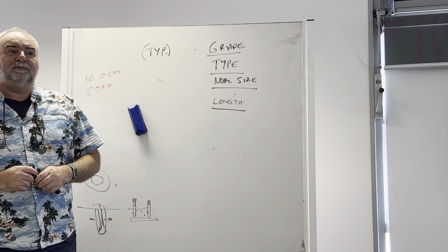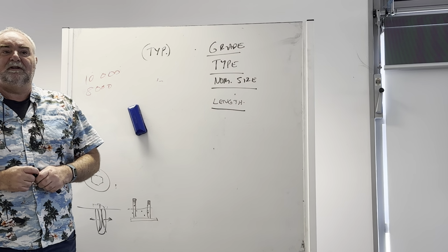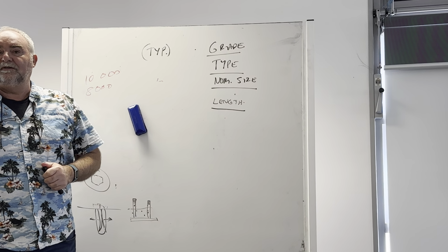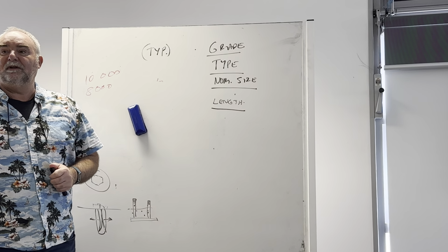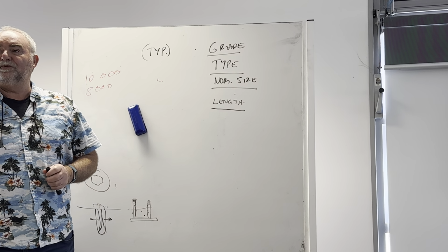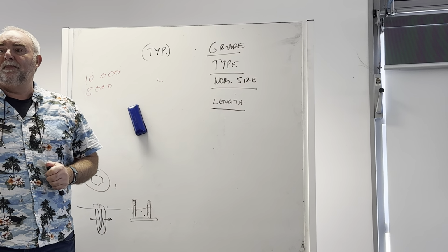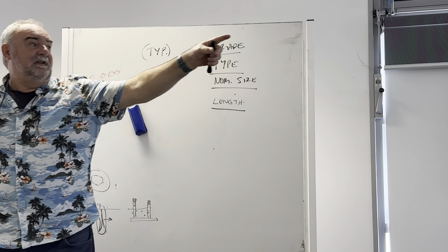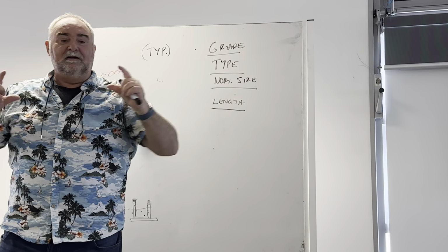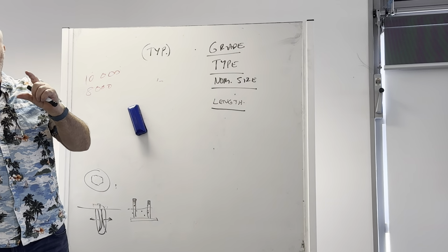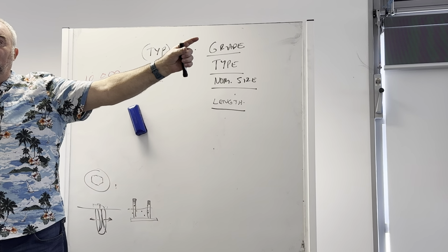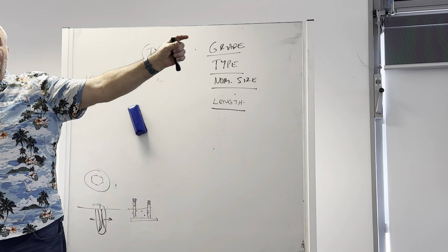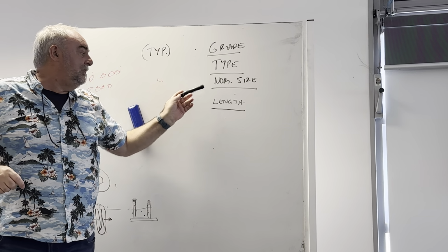So when architects put a smooth finish on their drawings, it starts driving the structural engineers crazy because they have to redo their calculations again to make sure buildings are going to hold up. If you had a beam from there across to the other side, 10 mil off the whole beam can make a big difference to whether it's going to hold up or break. So the nominal size is important.